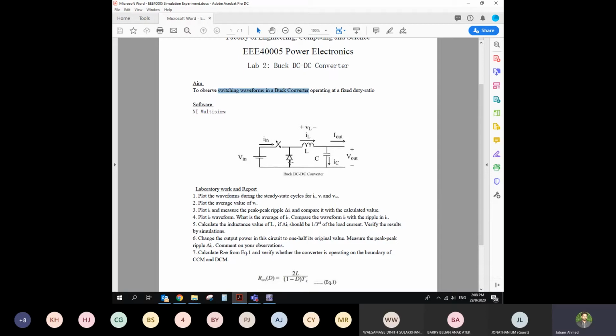Then this is a diode, and here the switch is working as a switch. Usually we use a Schottky diode, but a normal diode will also do fine for that. If I describe it basically without going deep into the equations, in the beginning when this switch is closed, the current will flow through the inductor, the capacitor and the load, and by that time this diode will be turned off. So this is going to be an open circuit here, so current will flow. This is happening when the switch is on.